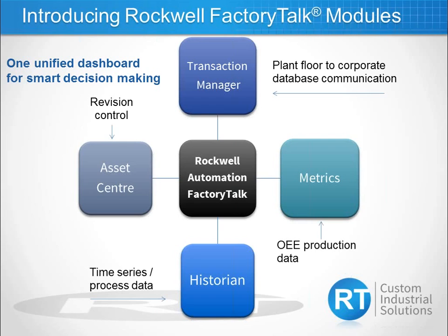So if we look at the modules, we'll call them modules because they really truly represent a nice little module that you have here. One of the things that we have is that database that's up on the corporate network. Well, how do we get that data from the corporate database down to the PLC? Well, that's where the transaction manager module comes into play. It can take a look at a PLC, or someone could hit a button on a screen that says, give me recipe parameters A. It goes up to the corporate database, brings them down and puts it in there.